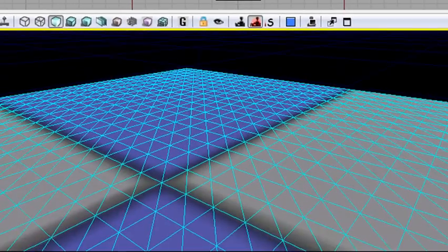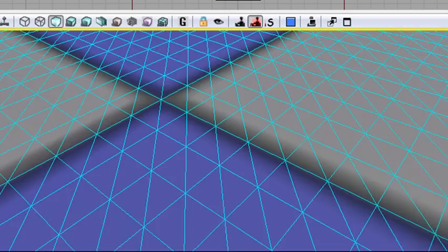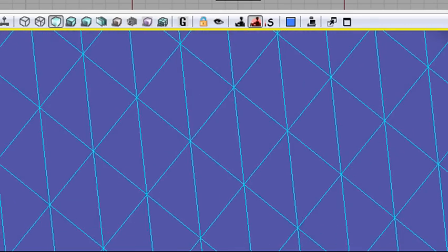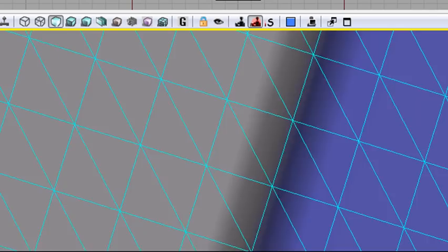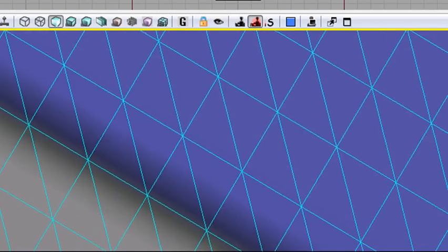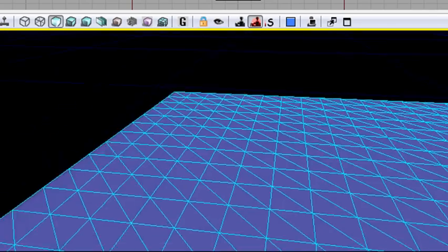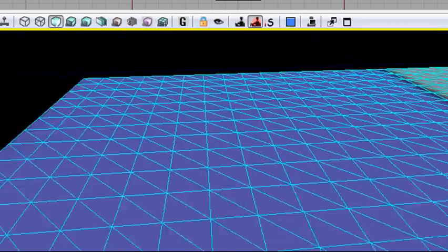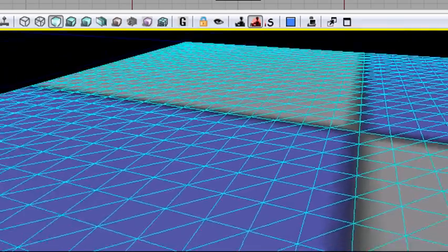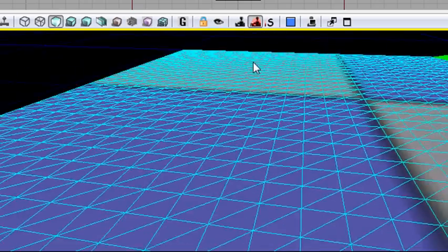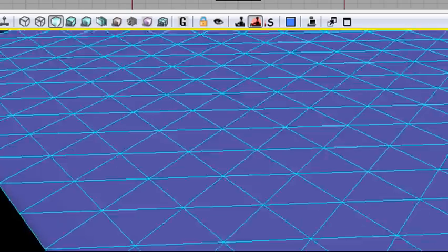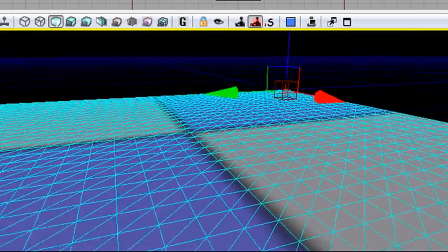So if I suddenly want to rotate it up so I can actually see it, I just rotate it up like that. See? Now I just rotate it completely horizontal with the right button. And with the left button, you just translate it along the surface. Let's rotate it back down with the right button. Okay? So just remember that. You want to go left, right. It's kind of like driving a car with two feet. So you can actually click with one to translate and with the other to rotate up and down and around. Okay, so remember that, and you can position your mesh any way you want to.